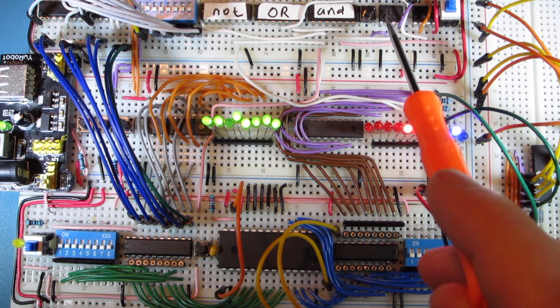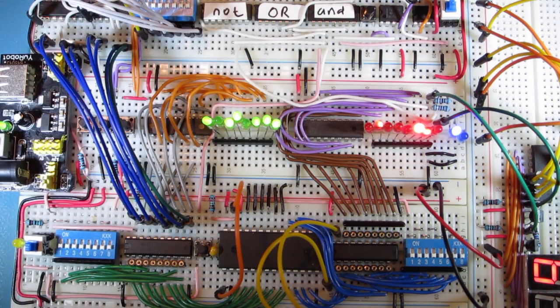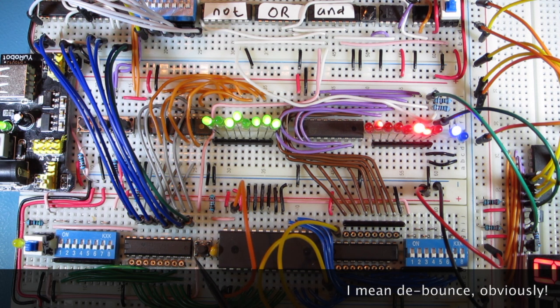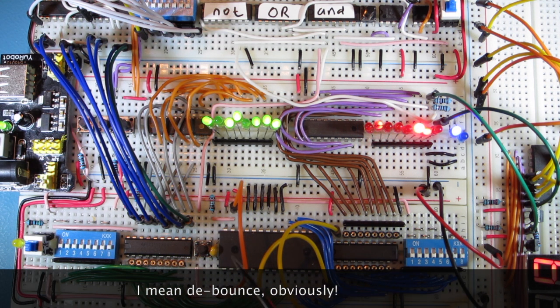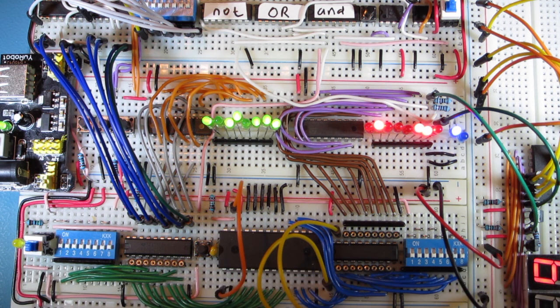There's a second 555 here, which is in monostable mode, which means if I turn the clock off automatic onto monostable, I can press the button and it does a single pulse of the clock. The reason for using a 555 in monostable mode to send a single pulse instead of just decoupling with a little capacitor like I have on the right button for the memory is to do with multiple pulses.